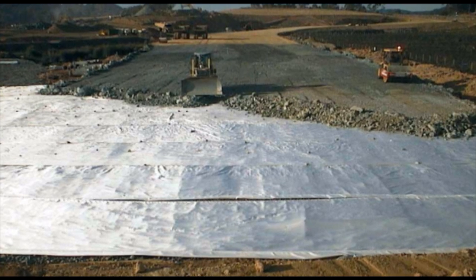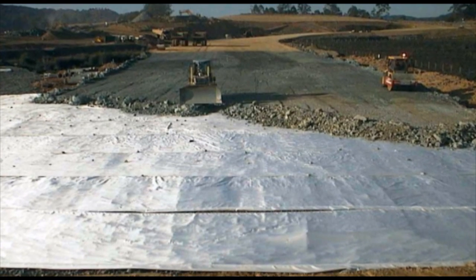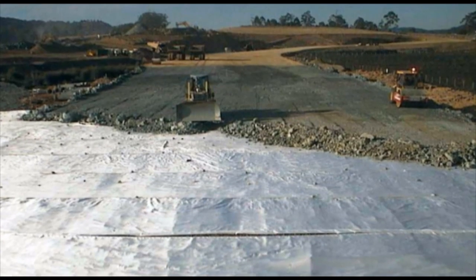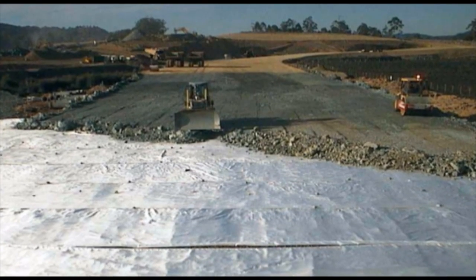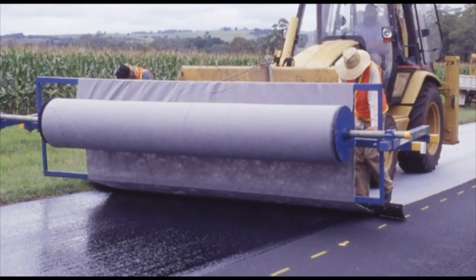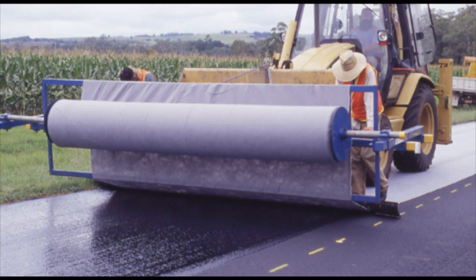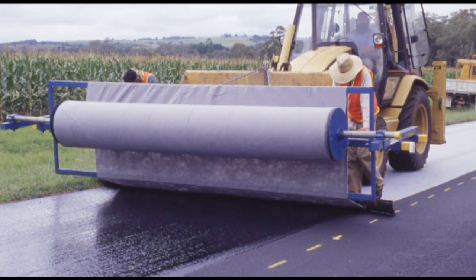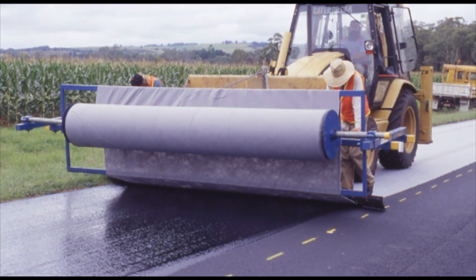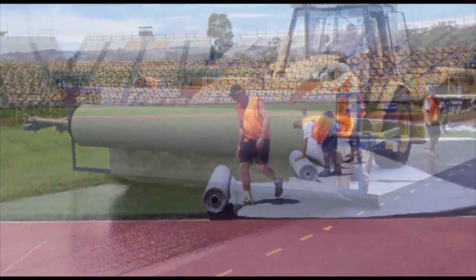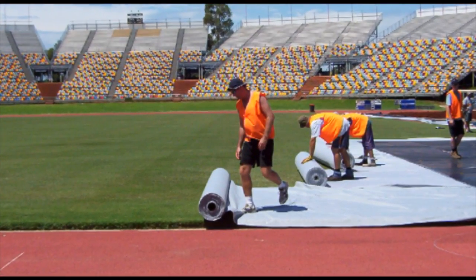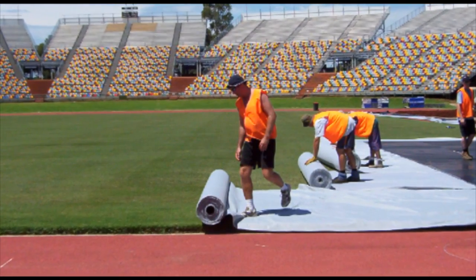To refresh ourselves about how geotextiles are used, let's look at a few of the most common applications. A high-strength geotextile provides reinforcement for weak soils under an embankment. A lightweight non-woven geotextile is being applied to a road surface to reduce water ingress and thus reducing cracking of the surface. A non-woven geotextile is simply being used to protect a sporting surface from temporary staging for a concert.